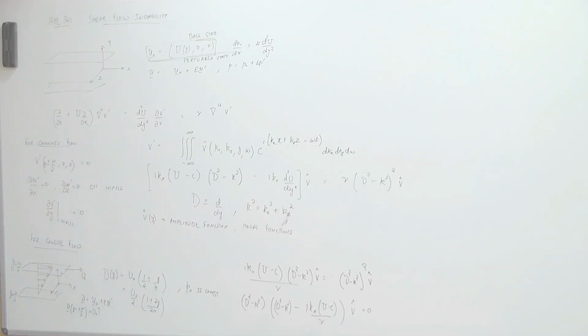Okay. The biggest mistake that most students make here is that they will see this u naught and they will say, okay, perturbation also has a boundary condition of u naught at the top wall. It is a perturbation. The wall is fixing the velocity of the fluid to be u naught. So, that means the perturbation will be 0 there. The wall is fixing through no slip. So, perturbation is still 0.